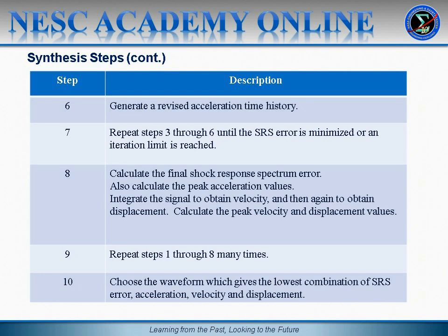Step number 6, generate a revised acceleration time history, and that's based on the previous scaling. Step number 7, repeat steps 3 through 6 until the SRS error is minimized or an iteration limit is reached. Step number 8, calculate the final shock response spectrum error.